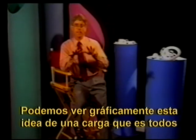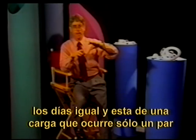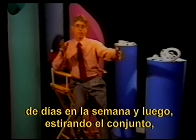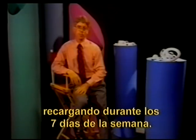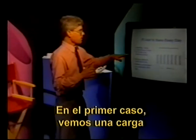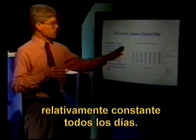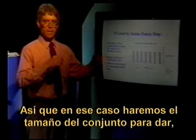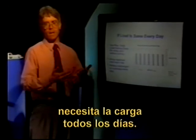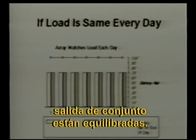We can look graphically at this idea of a load that's the same every day, and this idea of a load that occurs only a couple days of the week and then stretching out the array, recharging over all 7 days of the week. Let's compare the two and you'll see the difference that we get. In the first case, we can look at a load that's fairly constant every day. So in that case, we'll size the array to give, on the average, the same amount of energy that the load needs every day. So the load demand and the array output are balanced.